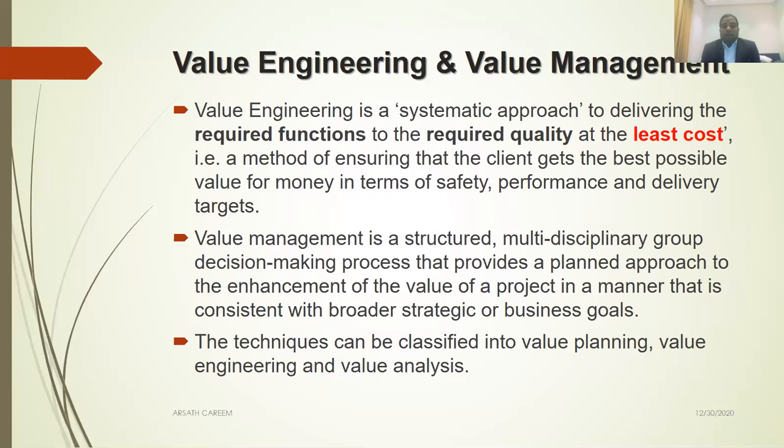What we are discussing are pre-contract cost control mechanisms. One of the mechanisms we mainly use is cost planning. We use cost planning throughout the design process. Unfortunately, your budget is over. You are not able to design the building within the budget. So what mechanism is available to reduce the cost? That is where value engineering takes place. Value engineering is one of the major tools to bring the budget back.